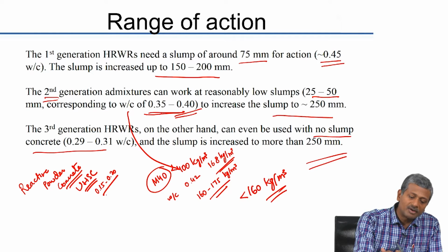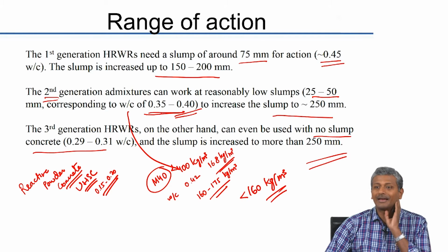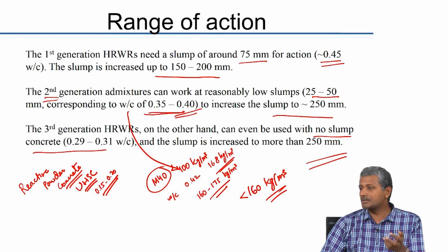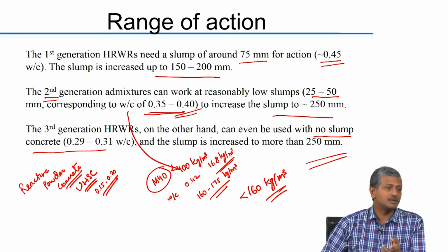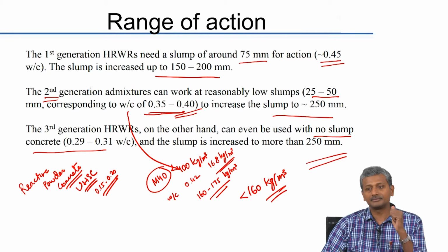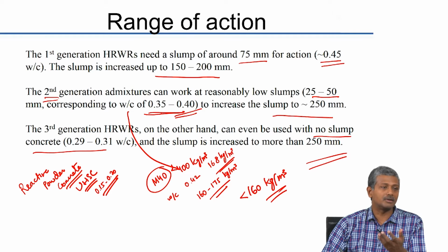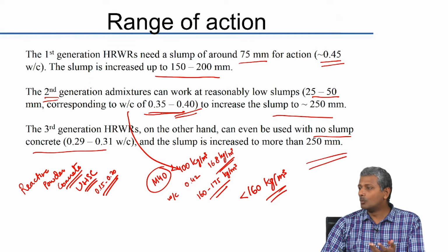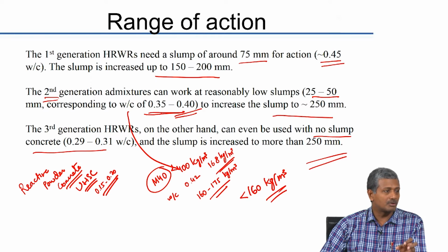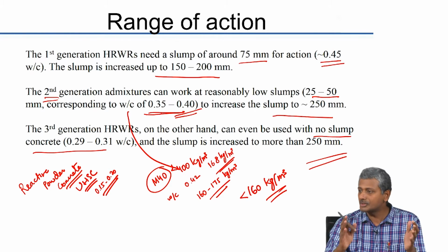of 0.15 to 0.2, and at that range the only admixture that can come about to give any effectiveness is the PCE admixture. And truly speaking, even with the PCE, the amount of the admixture required is typically of the order of 2.5 to 3%. So, you are not talking about regular concrete, and regular concrete would hardly use more than 1.5% of the PCE admixture. But when we come to reactive powder concrete, we are talking about 2.5 to 3%, very large quantities of admixture required to provide some degree of flowability.